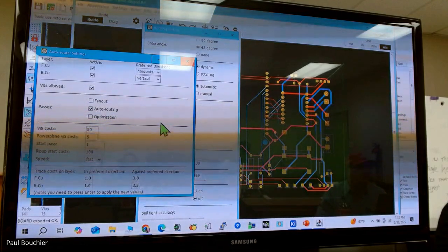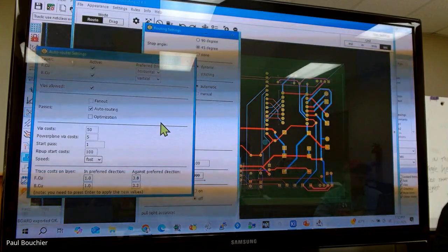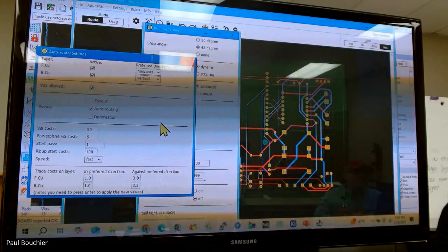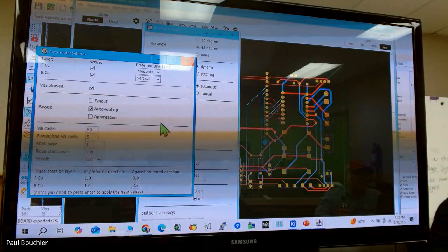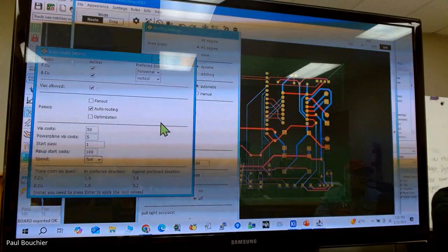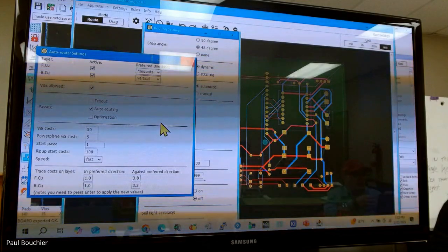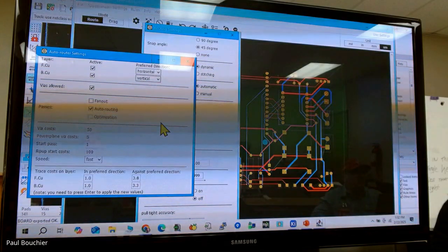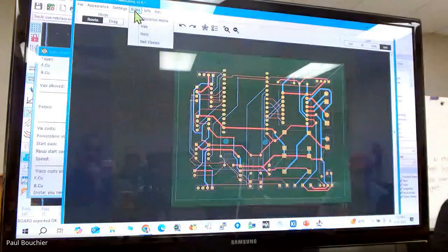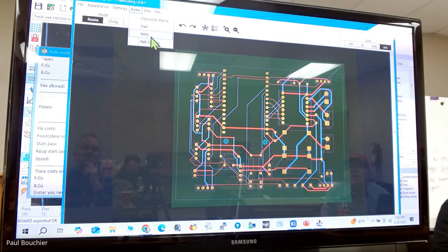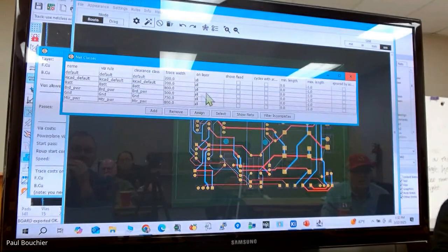I haven't made a toner transfer PCB in many years. And so I know that you wanted to minimize the jumpers. Since you're only on the top, I think it just puts a via on two sides of the line. But it has kind of no settings for how far the vias are or what size they are. You would think you'd have to. I think they probably inherit that from the design. You see, you have net classes. So, it has the rules here.